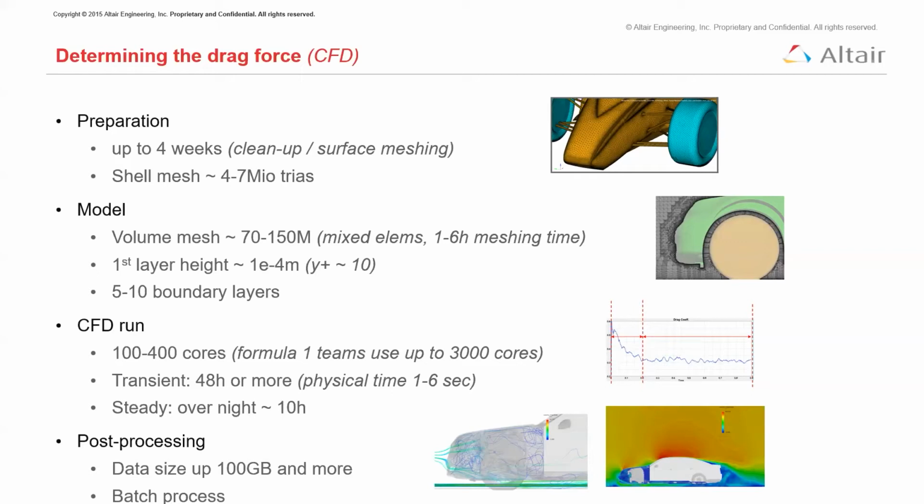If you're not familiar with this surface Y plus value, the best way for me to describe it is it's a measure of the distance from... okay, so when you create the inflation layer to capture your boundary layer outside of your model, you can imagine a mesh being placed on that boundary layer, and as the mesh grows outside from the car's surface, the element sizes are getting larger and larger, and your total distance from the inside node to the furthest outside node of that inflation layer is your surface Y plus value.